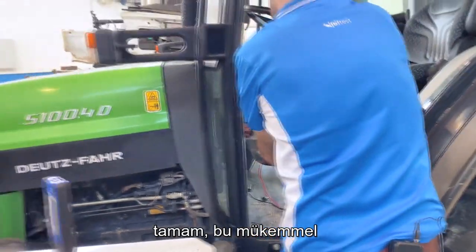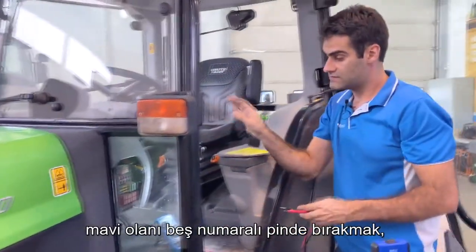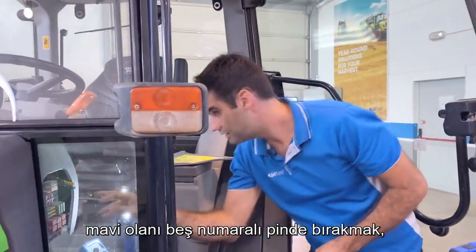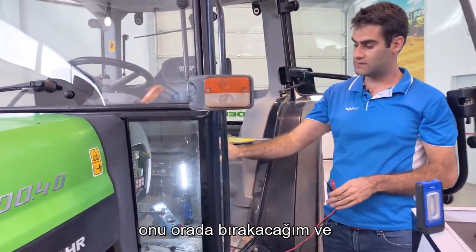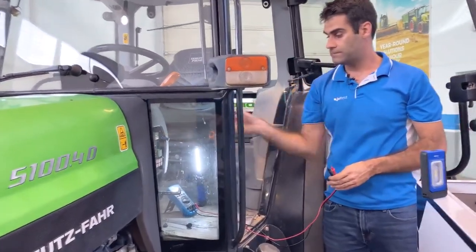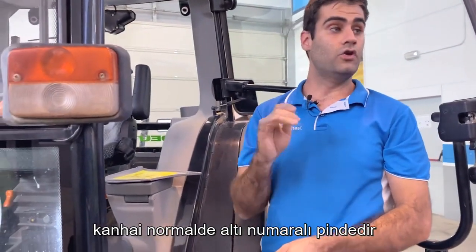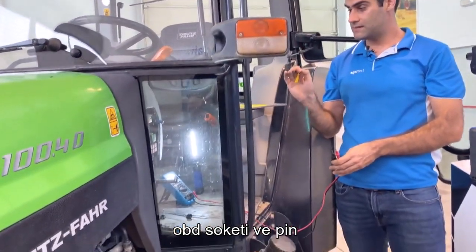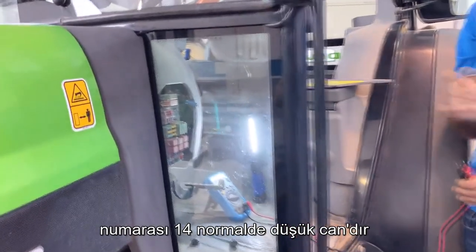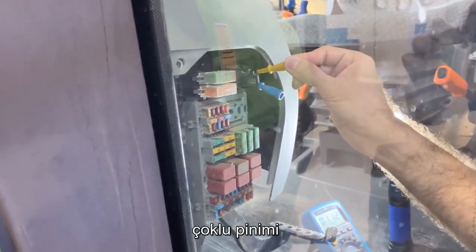Okay, so that's perfect. Now what I'm going to do is leave the blue one in pin number 5. 4 and 5 are both for ground, so it's good for me. I'm going to leave it there, and I'm going to use the yellow one to see CAN high and CAN low. CAN high normally is in pin number 6 in the OBD socket, and pin number 14 normally is CAN low. So I'm going to place my yellow multipin in number 6.